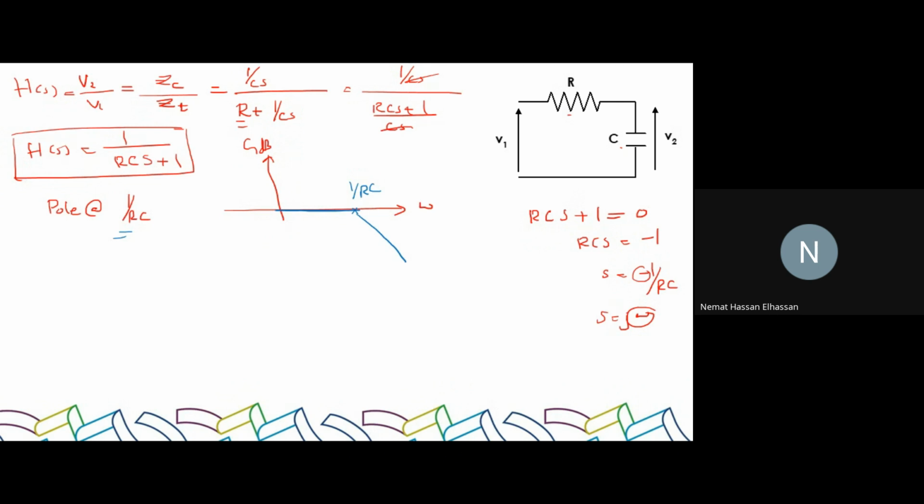So this is the rule of how we plot poles: we decide what is the value of the pole. And then from that point, which we call the break frequency, so 1 over RC is called the break frequency, we'll have a constant drop of gain. So this is gain in decibels. And in decibels, 0 decibel means 1 in actual numbers. Which means that if you look at this signal in regular gain, not in decibels, it has a stable amplitude at 1, which starts to drop at the 1 over RC frequency. Clear?